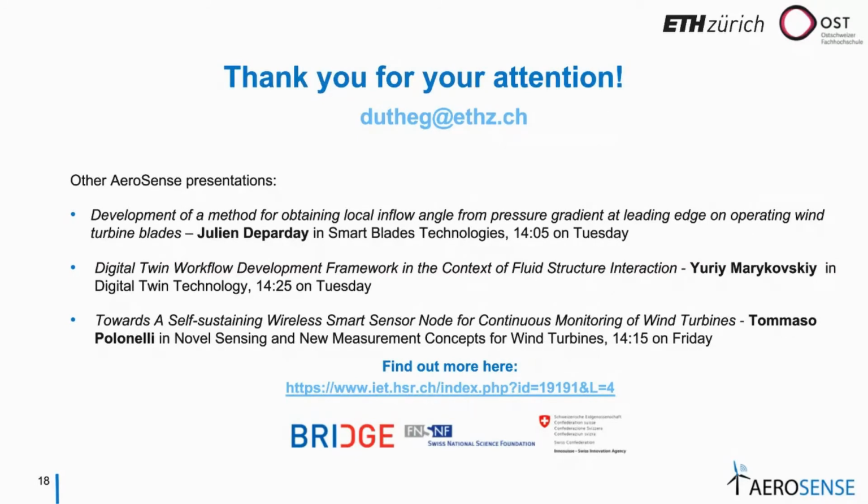By physically, you mean you did not change the actual geometry? We didn't change the geometry, not the mesh in itself, the geometry stays the same. And the reason for this is we didn't want meshing dependency to arise within the data set, right? So we want to avoid manually tuning the mesh ourselves. So we would only keep that as automatic as possible and not have mesh dependency issues within the data set.